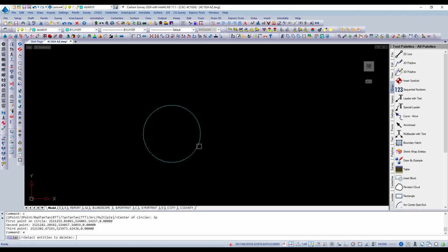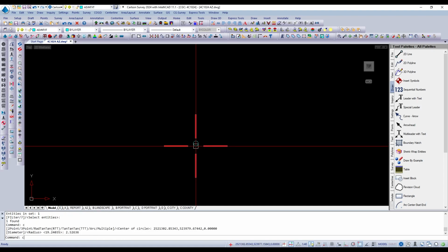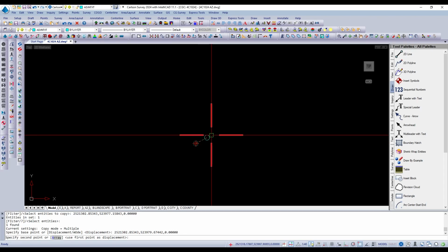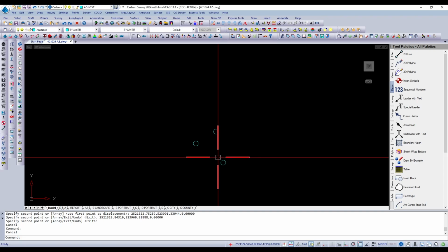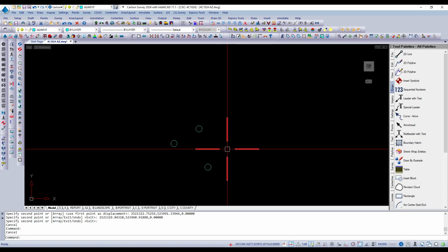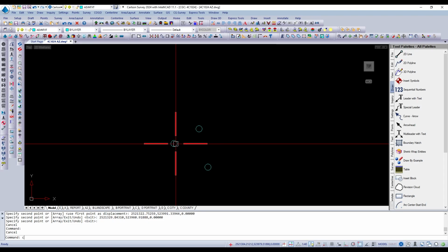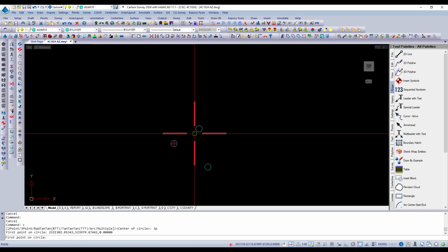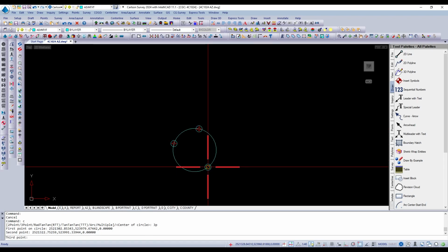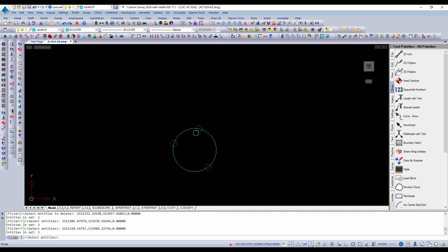If you have something like a drainage structure or a fire pit or something like that, let's say, and our field crew has shot 3 points on it to define the limits of it, or even a big pool, a hot tub or something. Sometimes pools are circular. You can quickly draw a circle through those 3 points that they collected in the field and get the radius of the fire pit or whatever it happens to be. Drainage structure, like so.